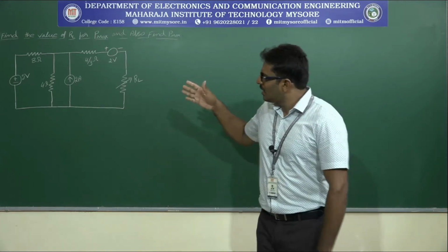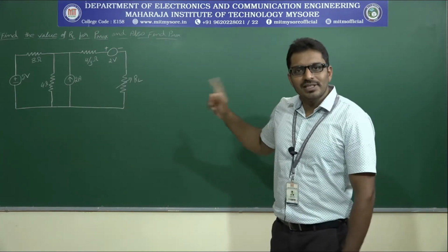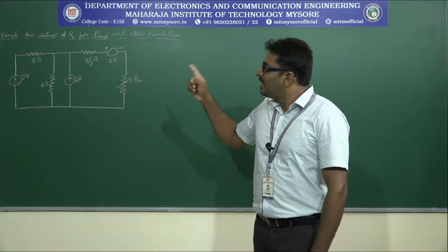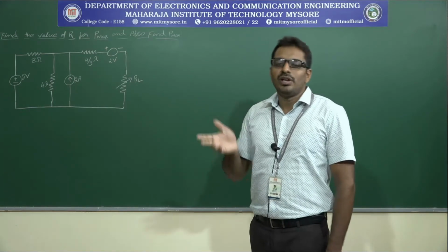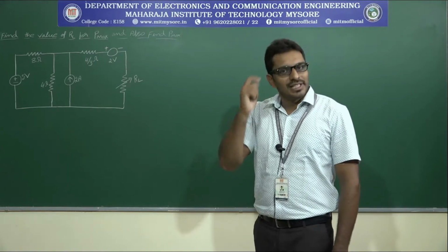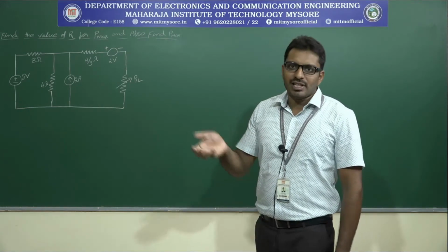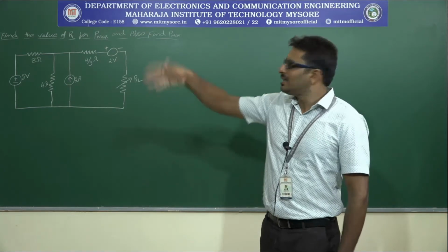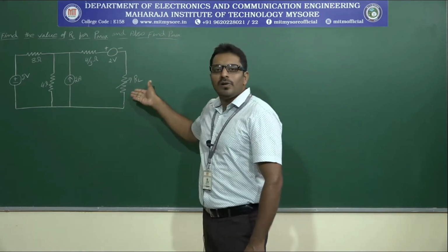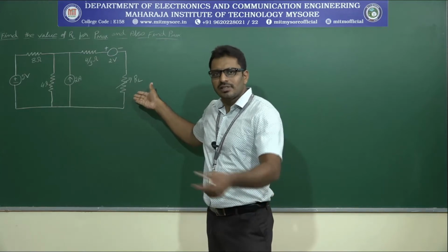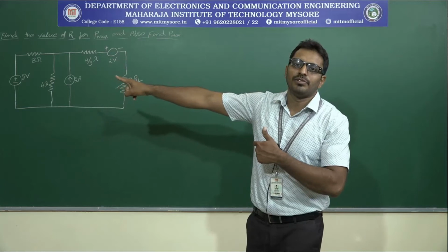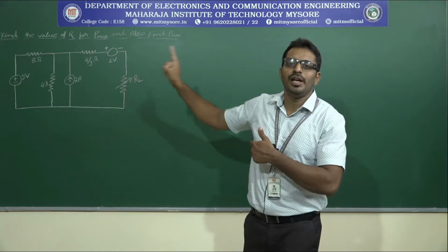By seeing this circuit clearly, it indicates this comes under case 1 because this is a DC circuit. The single voltage source is DC. Obviously there is an internal resistance, which is connected to a variable load resistance, an unknown resistance. That is what we are going to find: RL to transfer maximum power from source to the load.